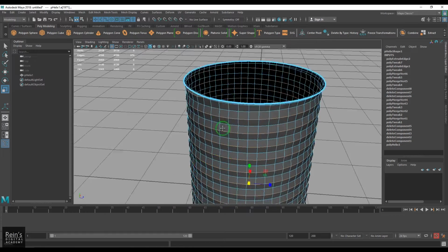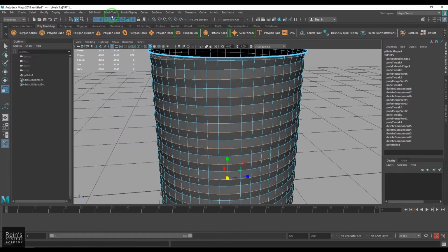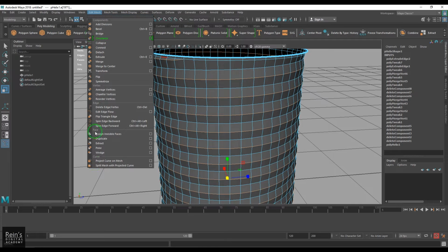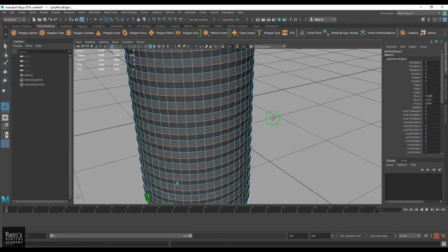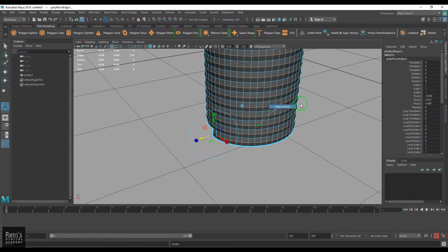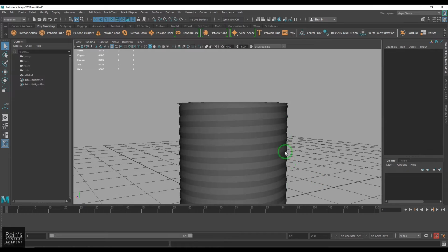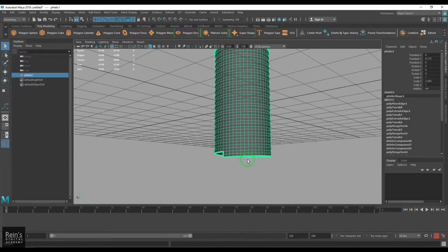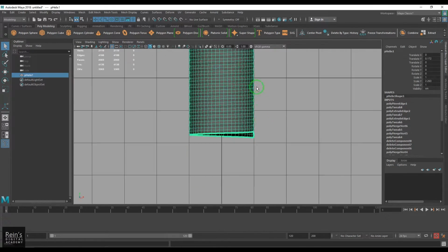So I'm going to select this line, and I'm going to use this tool called transform component, and then just bring that to the z-axis like that. Before going into that, as we have done on the top side, we should do the bottom side also.